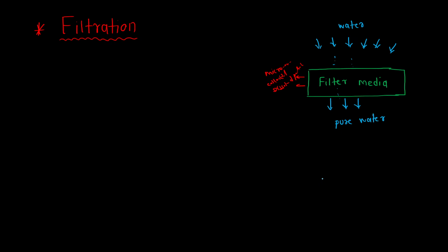Okay, so there are various types of filter media which are present. Basically in India we use sand filters, whereas in some of the foreign countries they use anthracite coal as the filter media. As anthracite coal is not available in abundance in India, we go for sand. Okay, so write down these points.